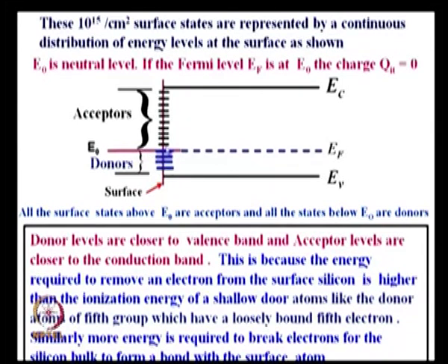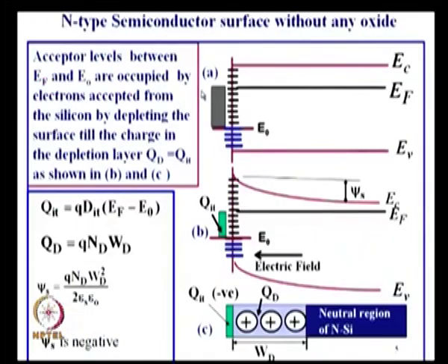Okay. So, the location of E_0 with respect to E_v or E_c is fixed. So, if band bending takes place like that, the Fermi level gap has changed from here, but the location of E_0 with respect to valence band is the same on the surface. Which would mean, because of the charge transfer from the semiconductor to the interface, the Fermi level has moved up.